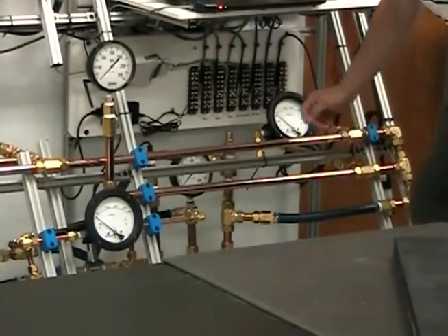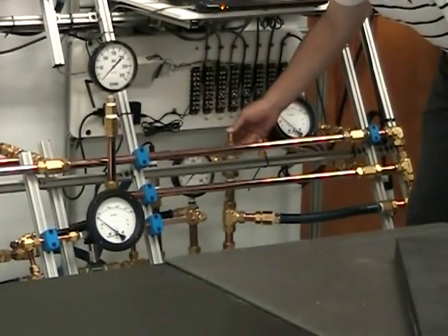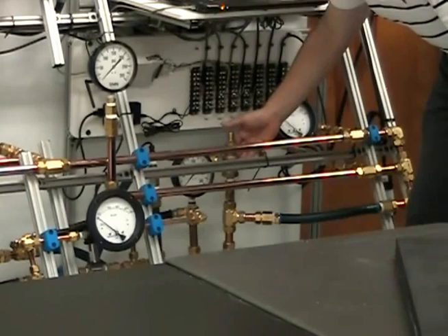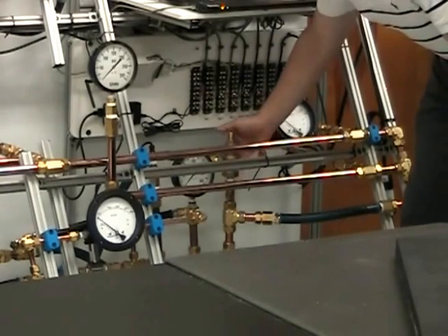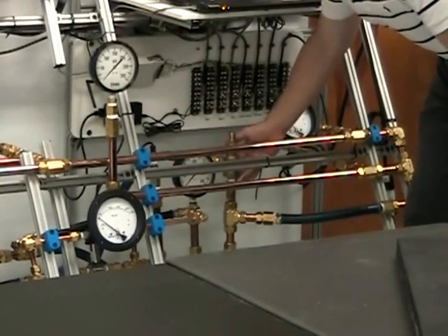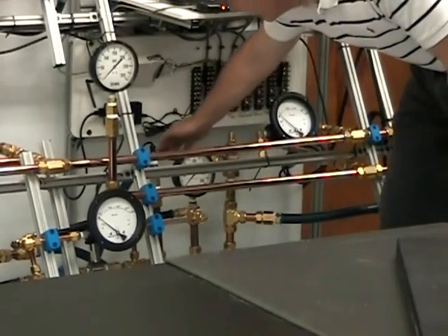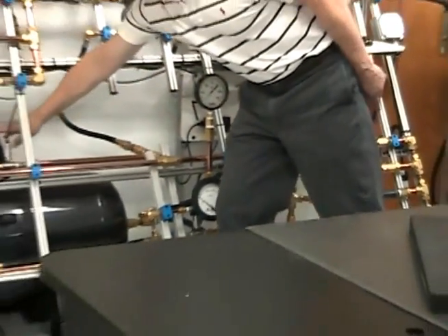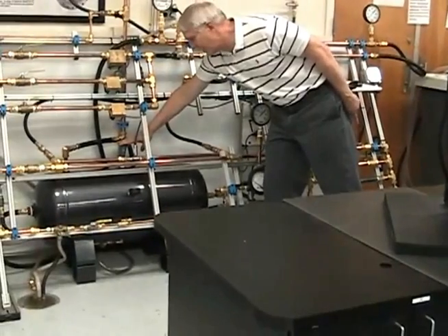Now this set of pipes down here is set up so that if we shut the flow off, or we shut it off too much, there's a bypass valve so that the pump doesn't get overloaded, and the water will go back through this tube over here and back into the tank over here.